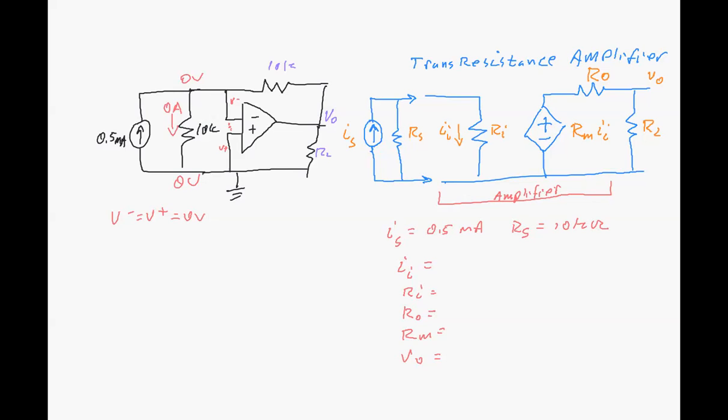Well, this current source here will ideally output exactly 0.5 milliamp. That's its job. That's what it does. It's going to send 0.5 milliamp out there, and we have 0 milliamps flowing down through there. So that means that all of that 0.5 milliamp wants to be flowing that way, right? It's just flowing straight on. And a current source is perfectly happy to have 0 volts on both sides of it. It doesn't care. An ideal current source will create any voltage across it that it needs to achieve that 0.5 milliamp current.